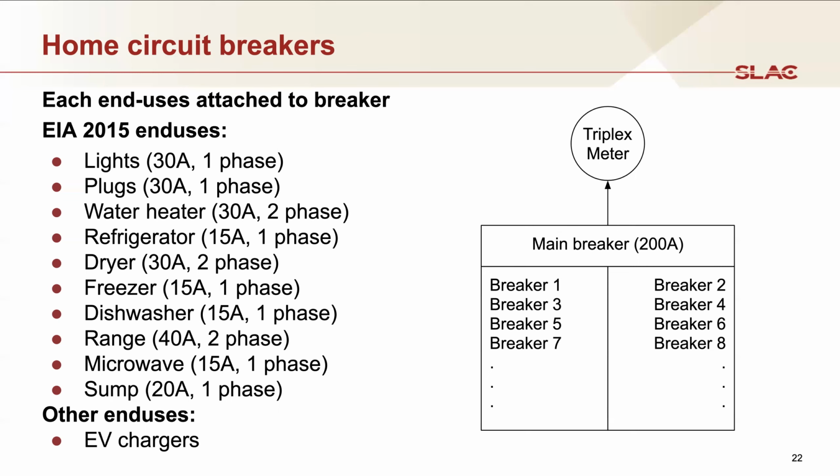And it helps mitigate solver problems when you have end uses that consume ridiculously large amounts of power. Because if you put too much load on the network, the solver itself will fail, unable to converge. So by having breakers open circuits that have excessive loads, that helps mitigate that to some extent.